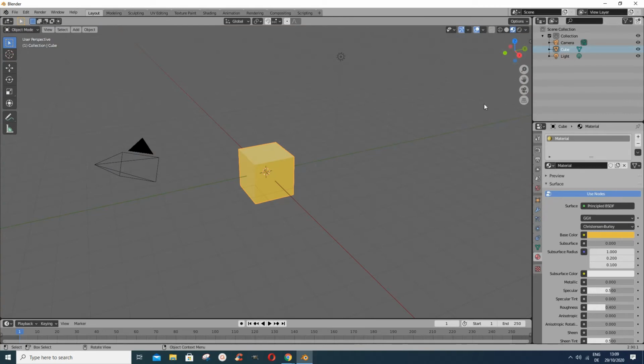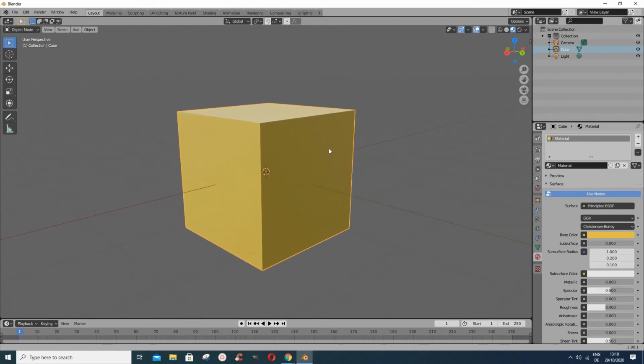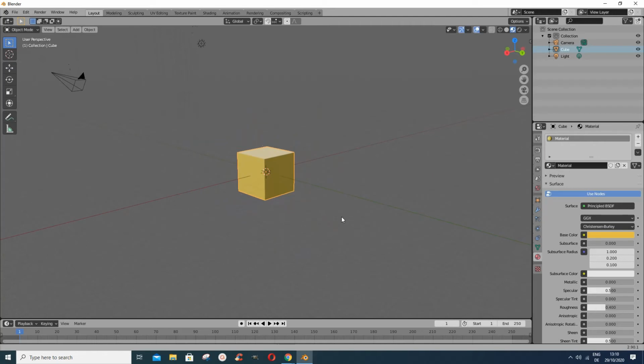Now last time I might have forgotten to tell you, of course, if you want to zoom in, you hold control and use your middle mouse button to zoom in or zoom out. You can also use this zoom in and out button. When you press this, it will help you to do the same thing. You can move in and out. If you use this move view button, you can move the view up and down like this as well.